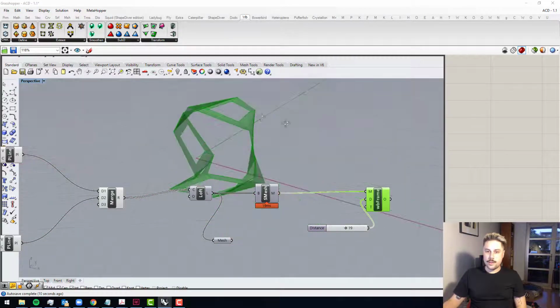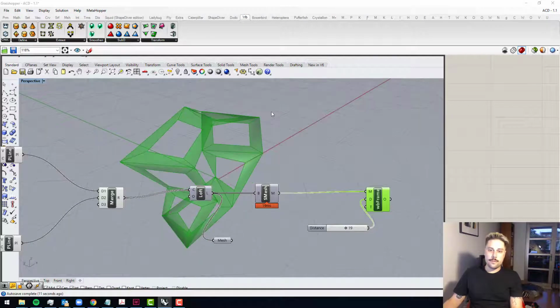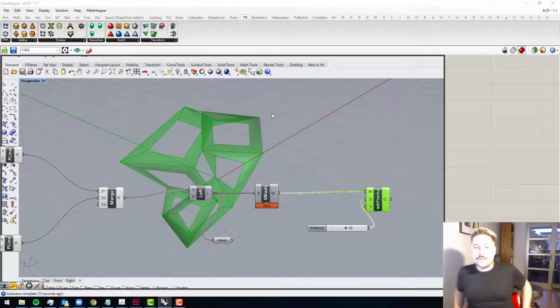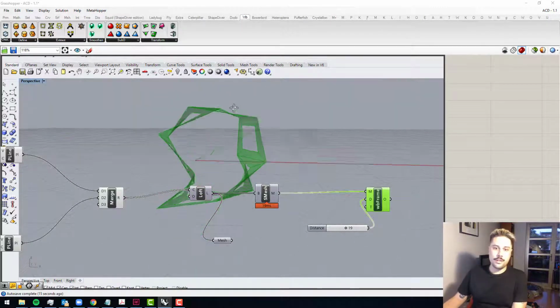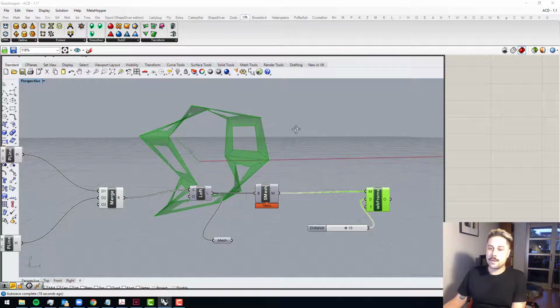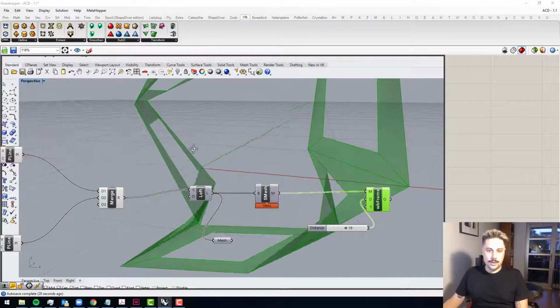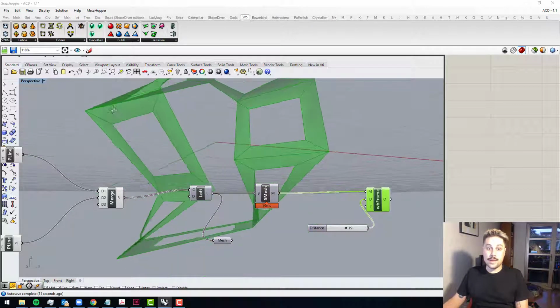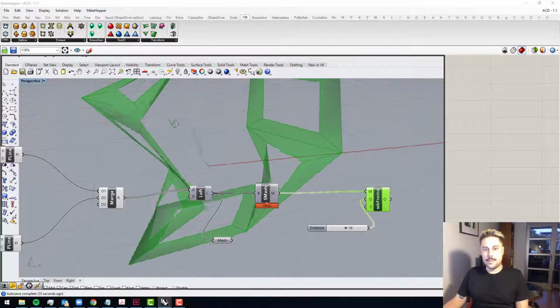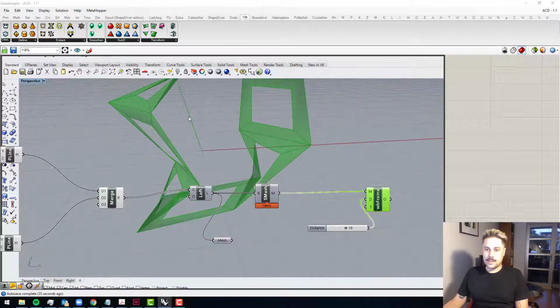So this will become this weird little ring that's got a few holes in it. And this ring currently has a thickness of 0. These mesh faces don't have a third dimension to them, so essentially it can't be made at all.